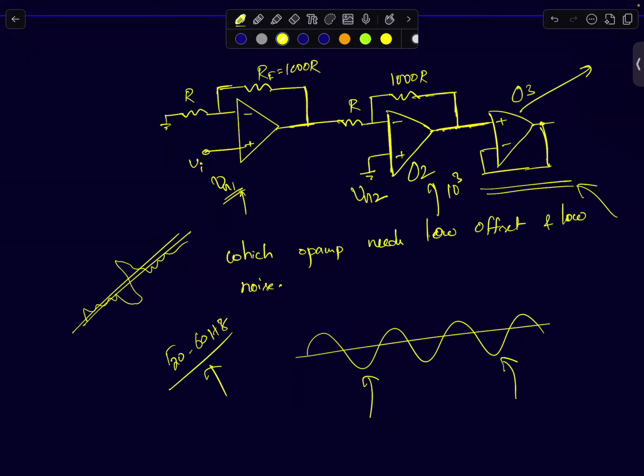Even the supply generator that you use in the lab will contain some unwanted 50 hertz noise. Maybe you can think of a way of canceling this, because you know there is only noise at one frequency. You can just keep on adding some signal with the same frequency, but slowly change its amplitude till it cancels out. You can do that.